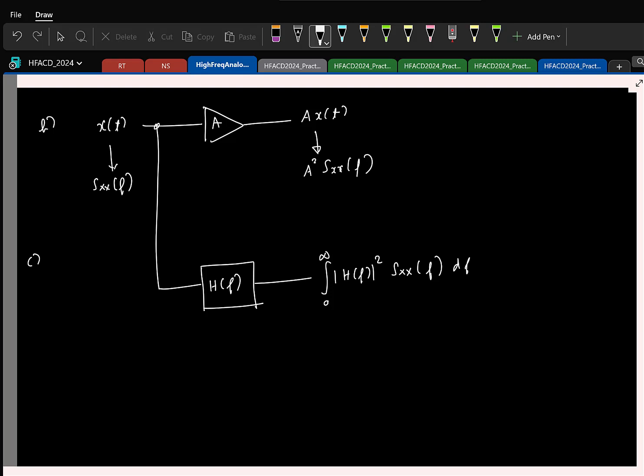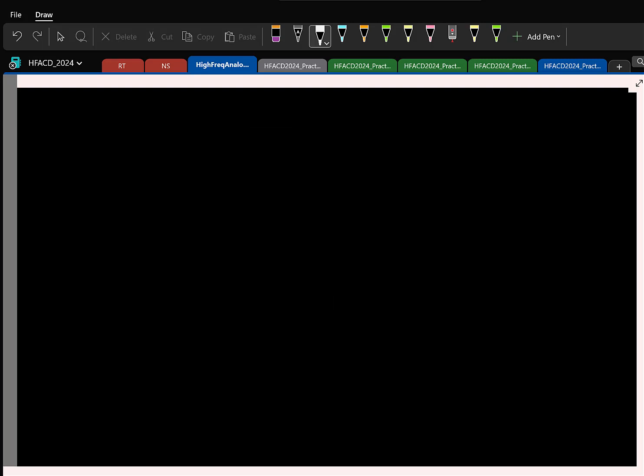So as we saw, the resistor is generating this noise, and typically if I go and measure this voltage across a resistor, I explained it as measuring a short circuit current. You can also measure the open circuit voltage. Ideally it should be 0, but in practice it will have fluctuations, right? And that voltage, again the mean is 0, and if I look at the power spectral density, it turns out to be a constant, which is 4kT times R. It's one-sided PSD.